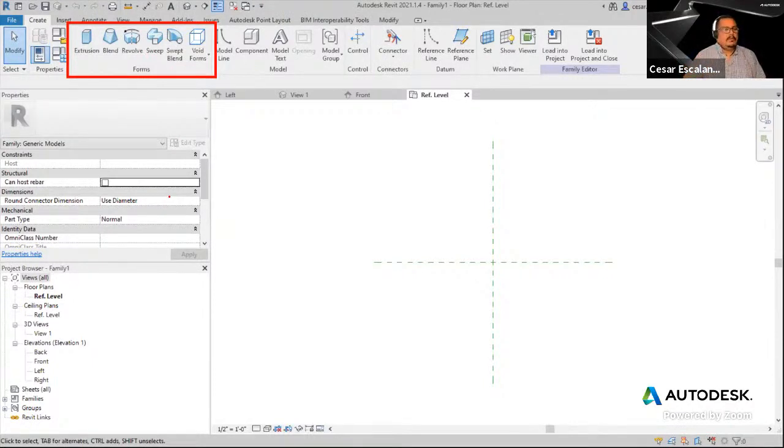The profile is something that you build using sketch lines. And if you remember, if you've done floors in the past, you probably edited the profile of walls in the past. Sketch lines are the boundaries of solid geometry. And to properly create a profile, the sketch lines need to be in a closed loop, and they don't need to overlap, right? And so you can create solid forms.